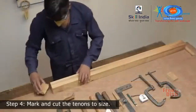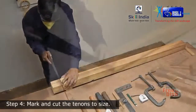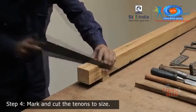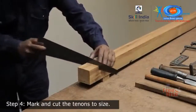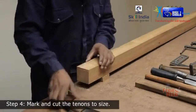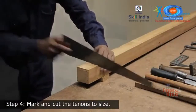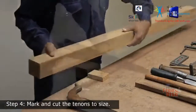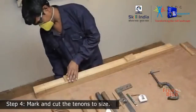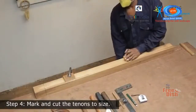Then, support the wooden piece on the bench top and start cutting with a handsaw along the waste side of the line till the shoulder line on both the edges. While cutting, take care not to overrun the shoulder lines. Reset the tenon member, cut down the edges on the other side. Then, secure the tenon member to the workbench with a G-clamp and chisel out.